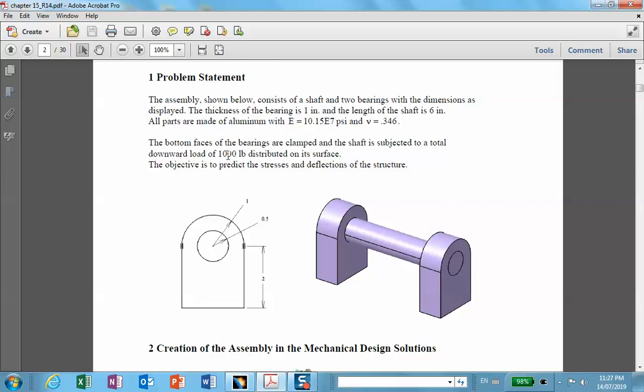Now I can see how you can apply perhaps a load of 1 pound at the top, but it's going to be very difficult to apply a downward load to the points below the shaft at every node worth 1 pound. So what I'm going to do instead is make a stand in the middle of the shaft, and then apply that load. Like I said, I'm not going to use 1,000, I'm going to use 200 pounds on that stand.